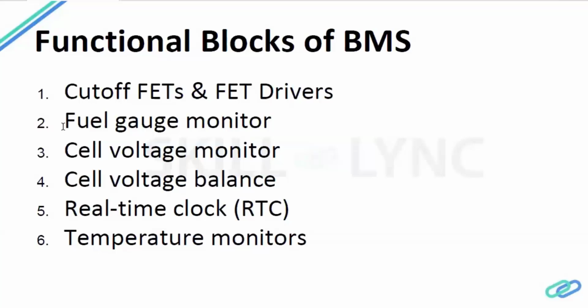Okay, so we will have cutoff FETs and FET drivers, which will help us cut off the battery pack from the other ECUs. The fuel gauge monitor will be used for checking how much capacity, how many coulombs, and how much voltage has been left inside the battery. So these things we will measure using the fuel gauge monitor.